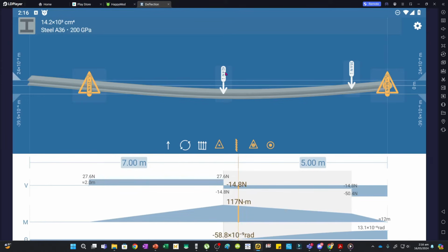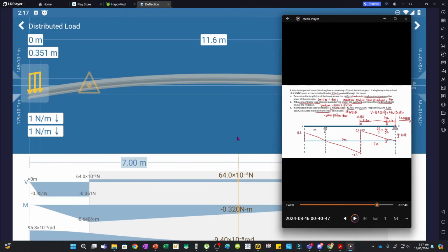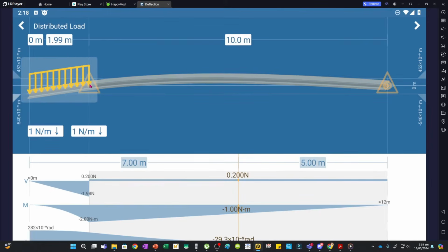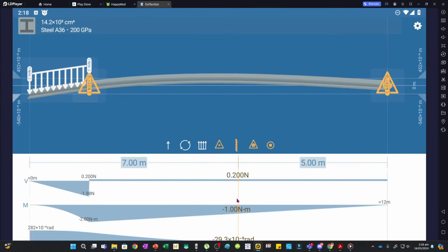And so you can try this app so that you'll better understand the locations of your loads. You can use this for other examples. Now, just another input, we know that if we apply forces at the overhang, then the shear at the midspan will be positive because this has positive ordinates right here. And so if I extend this up to 2 meters, the shear at the midspan must be positive. That's why this is positive.